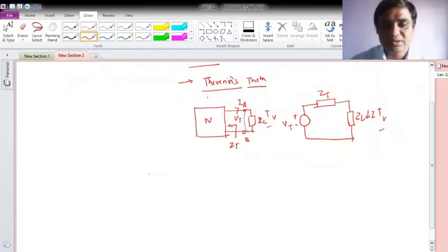We solved that in the S domain, because if you solve in the S domain you can solve it quickly, instead of writing the equations as differential equations and going with the solutions. So I prefer the Laplace domain, which takes very little time to solve. Also, you can use the phasor approach if the sources are sinusoidal. So let me take one example here.